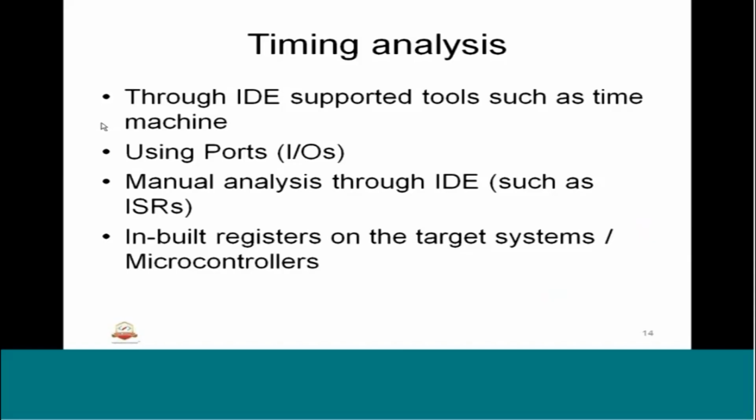The IDE, an integrated development environment, such as Multi, Lauterbach, CodeWarrior, etc. All these debuggers have inbuilt time machines or trace machines, and that will be used. That is helpful in finding the timing requirements by unlocking code, putting in a breakpoint, and measuring how much time it is taking. So we can validate with the help of that.